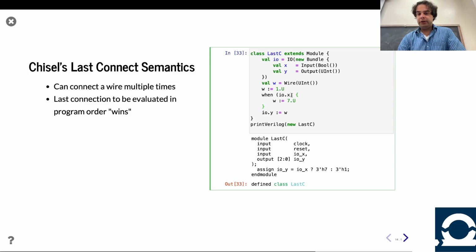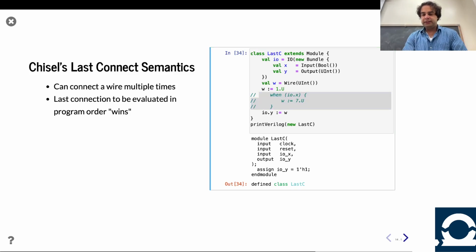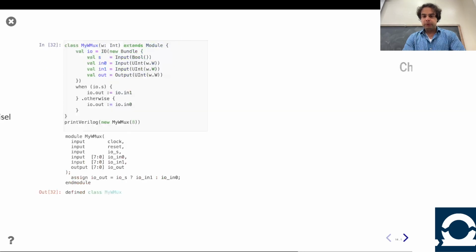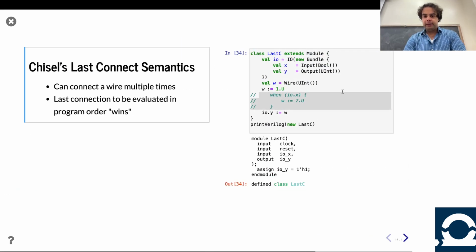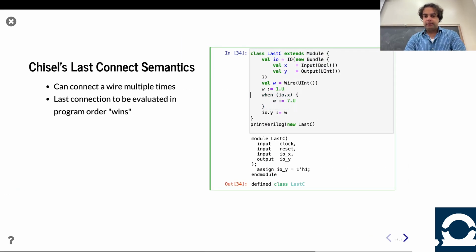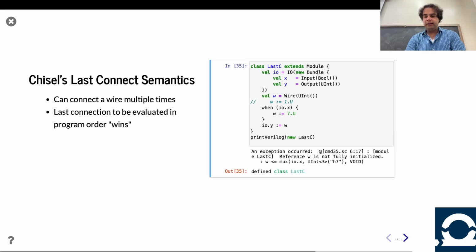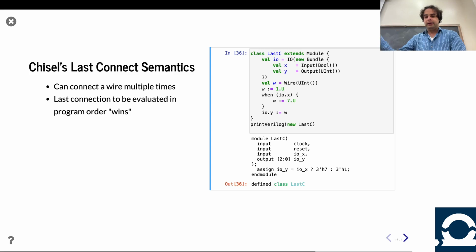Cool. And yeah, you can imagine all sorts of things, right? So of course, if I don't have the when statement, it's just always going to be 1. Oops. If I don't have the default value, it's going to yell that it's unspecified. I need to have all cases specified. And so yeah, rather than doing else when, sometimes it's easier just to give a default value and then conditionally override.